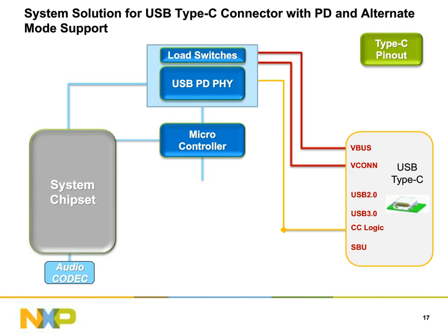Now you can imagine, along with the PD5 and MCU, you may need some load switches on your main power line. So what are load switches? Load switches automatically isolate the connector from a faulty source or a load, and it protects it from over voltage or over current or over temperature. So we see now that the VBus line can be negotiated up to 20 volt 5 amps.